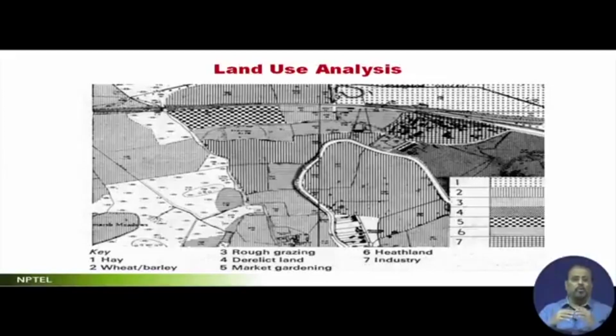In the whole design process, when you are going to take these decisions, for each one of them, one suggestion I keep, you take it very seriously. If you are analyzing with respect to land use, then you must shut off all your analysis for the rest. At this point, you are focusing only on the land use analysis. You are not checking the slope, the contour, the hydrology, or anything else. You are checking only land use. So you should shut off from all other analysis, focus on this analysis, and whatever transpires from it, write it down in inference.